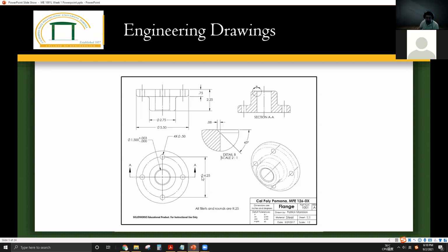That's why it has the diametrical sign on it. If it doesn't have the diametrical sign, you missed it or intentionally skipped it, that means these two holes are 4.25 inches away, and the other two holes are not regulated or not defined. The position of those two holes is not defined. Okay, so those are just some common practices to make your drawing look neater, and at the same time not over-defining anything.